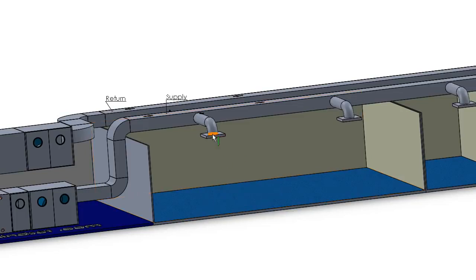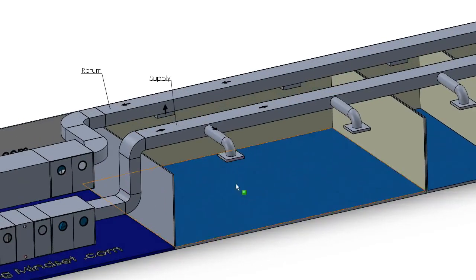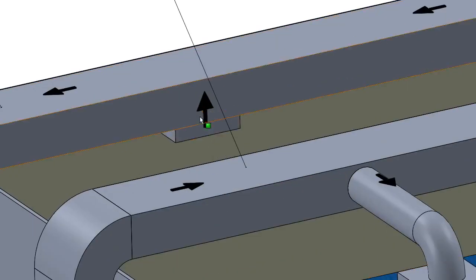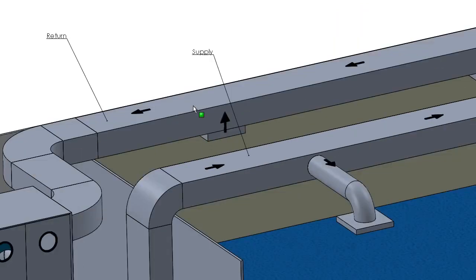So you've got to maintain certain conditions, which will be agreed on in the lease of the contract as well, and also the level of fresh air in there as well. So there'll be sensors in this room measuring the amount of CO2, the temperature, etc. And then over the back here we've got another grill, and this is going to the return ductwork.